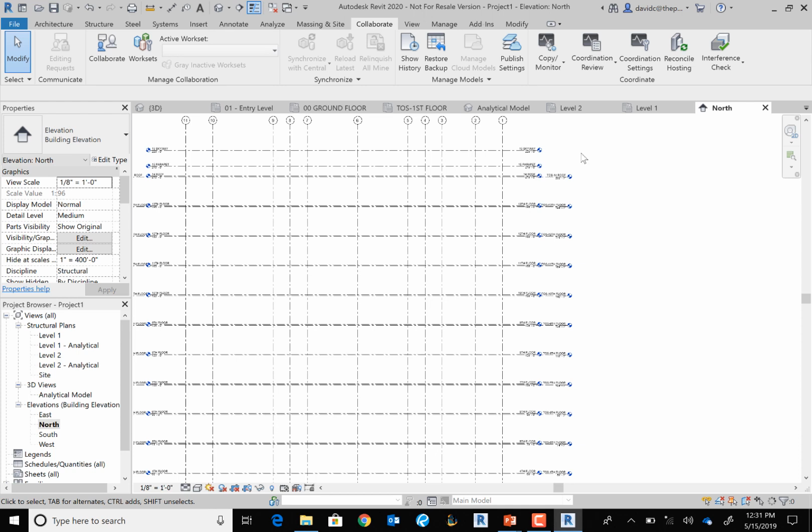And that's when you can go ahead and disassociate that a little bit, drop it to your top of steel. Or, if you want, leave those as architectural levels, right? So when those move, you can also constrain maybe your top of steel levels that actually have your structural views. You can constrain those to stay, and when the actual architectural levels move, they do as well. Okay, so that's kind of one way to do that.